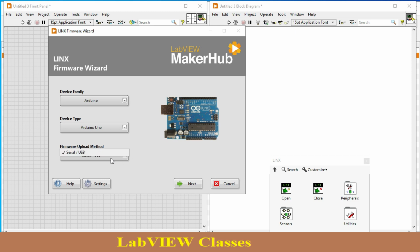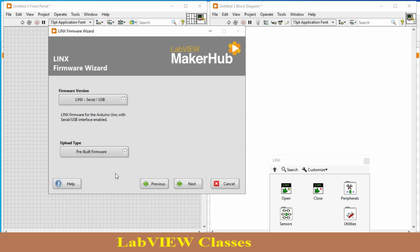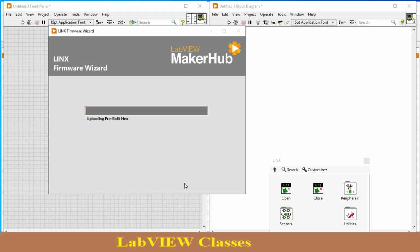Okay, and over here you just need to select how you upload your code. There are three options: USB, Wi-Fi and Bluetooth. Right now it is USB, so just press next. Over here it needs your COM port. As you see over here, I just select my COM port. Next, over here we have a pre-built firmware wizard. Right now I'm not using it. I'm just uploading the basic code inside it.